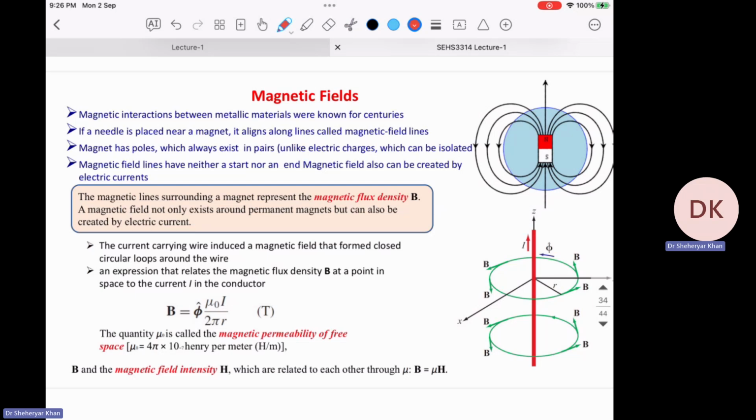They're heavy, not because of the copper, but because of the iron. We use iron plates and wrap the coil around the iron. So the flux increases, and you have a secondary coil on it, and the flux goes smoothly towards the secondary coil. We will later look at why we do insulation between plates, what eddy current is.